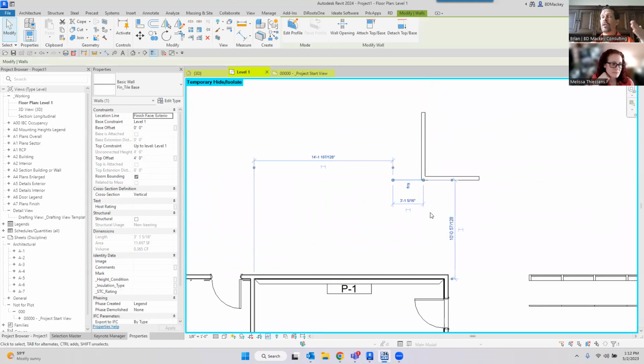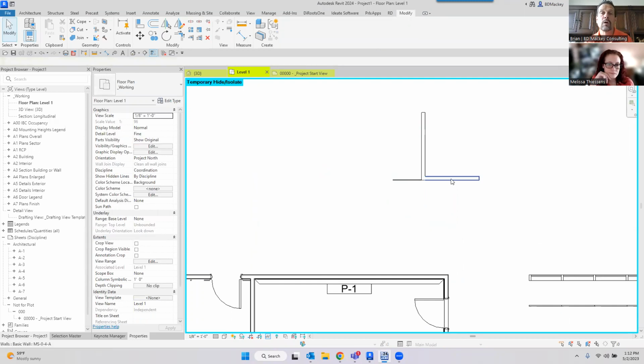Personally, I've only been on one project where I suggested using them, in a building that had elevated floors. We had a raised floor system at 2 feet, and everywhere there was a wall, they had to install a metal plate underneath it, and the elevated floor was always 2 feet. So we had a 1-inch thick join there, and we used it on every single interior, and it worked okay. There were a couple of scenarios where it didn't work, but for that case, it was all identical. It was exactly what you wanted to do, and it wasn't bad.